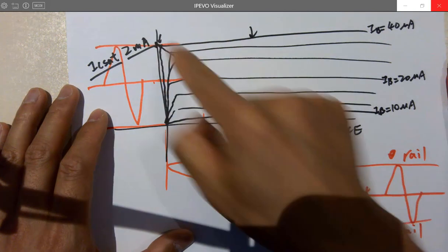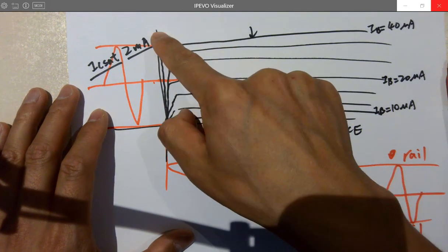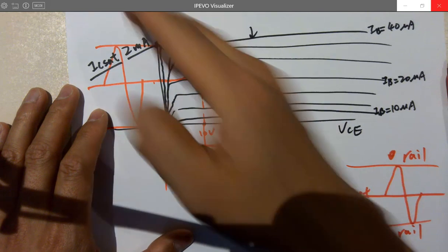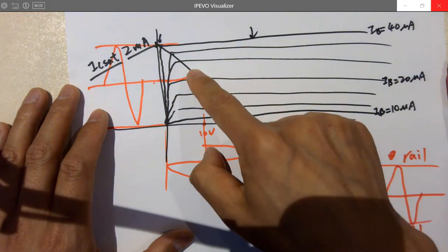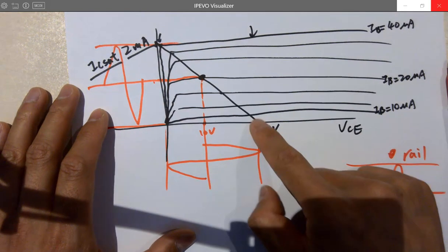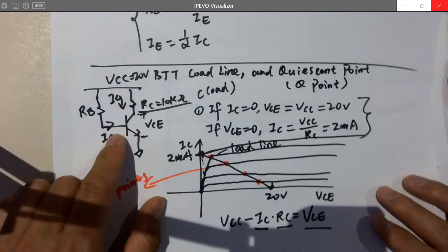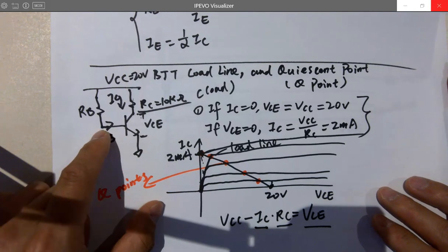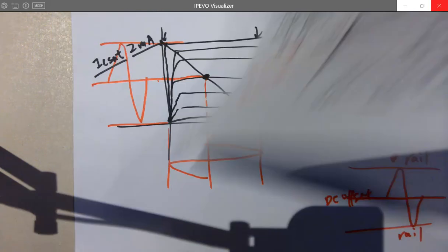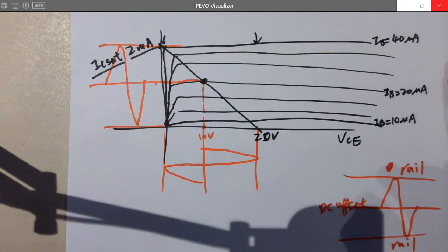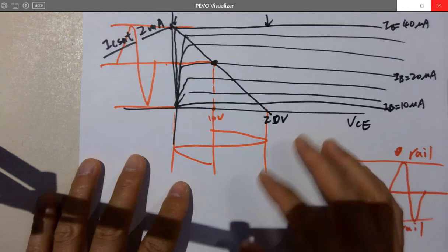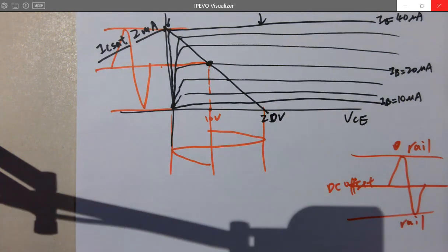Can this line make an IB change? No, so along this line, is IB changing or not? Yes, see, IB is changing. IB is the input, B is the base. You have a DC voltage here, you bias it. That's why it's called the Q point, quiescent, whenever there's no alternating signal to bother it, just sitting there.